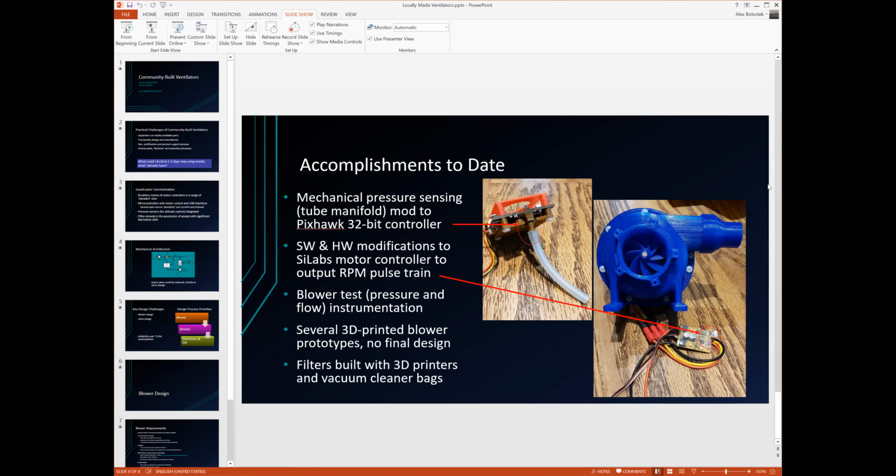Yeah, I'd just like to make a comment with regard to the turbine thing. My experience with turbines is typically at much higher flow rates and differential pressures, and they tend to be quite expensive. And the low cost ones, inflators for instance, don't seem to have the duty cycle or the robustness necessary for the application in a ventilator.